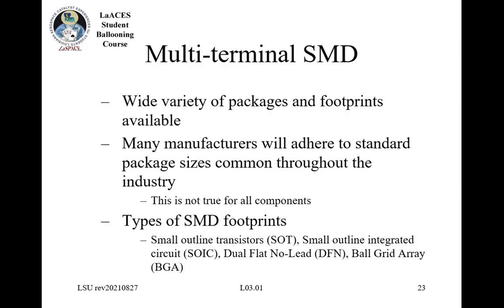So multi-terminal, this is just for different types of surface mount devices. And this is more dealing with the integrated circuits. There are different things you might see, like small outline transistor. These are just different footprints: small outline, SOIC, DFN, the ball grid array. By the way, if you see a ball grid array, you have to send that off to a company to solder it, because the leads are all underneath the device itself. So try to avoid those. Land grid array, ball grid array, don't get it unless you know you're going to send it off. Okay, so that's the end of